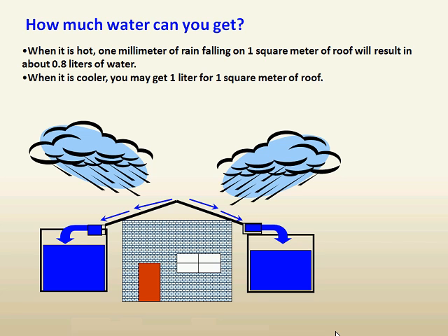If you're going to store, do you have more storage to capture all the rainfall, because then storage gets expensive, or do you have less storage and are more trying to bridge the gap during drought times? So there's a little bit of a trade-off, and then you're going to have to decide what kind of time step you're looking at. Anyway, you can get a fairly significant amount of water off of a roof.